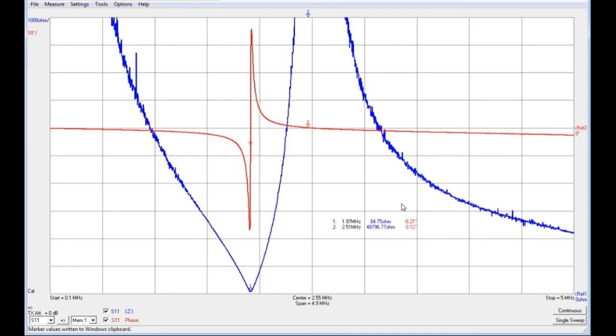So in effect, we are sticking a coil on top of the VNA with minimum influence, minimum coupling, and that allows us to measure much more truly the properties of the coil itself. But of course, in running, we're not able to actually do that. I mean, we can't just stick the coil and drive it that way and expect to couple lots of power through it. We need to magnetically couple the magnetic field of induction between the primary, as though in the transformer effect, to the secondary, and then we can pass large amounts of power.